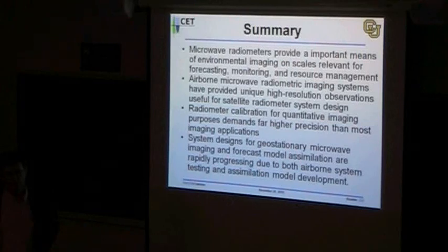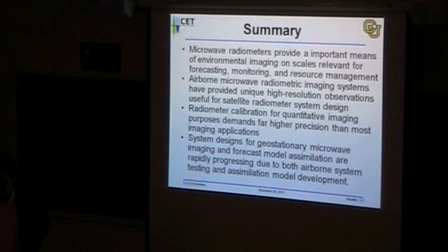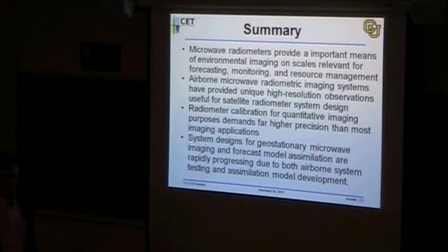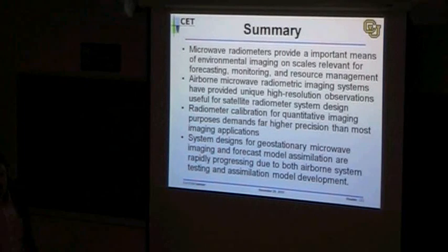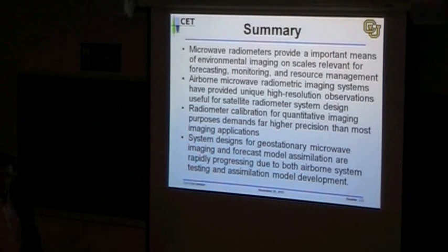What about the airplane base? Now that's a little bit different because with aircraft the trajectory is not so regular. We do have inertial navigation systems that provide us data sampled, that is position data, heading data, location data, at about 60 hertz. And if you pay the price, you can get that data sampled to angular precisions of about 0.01 degrees. And that satisfies all your requirements.